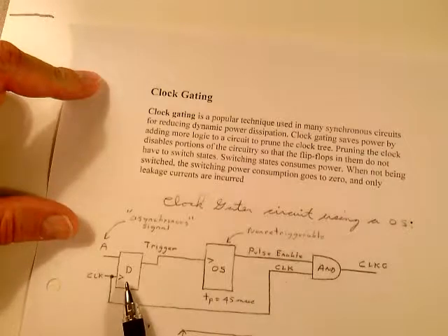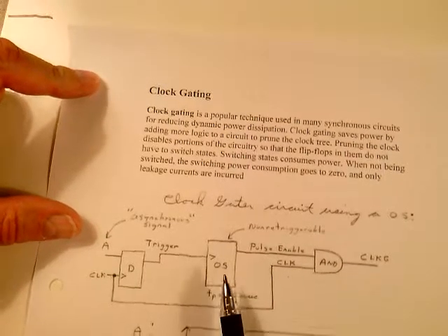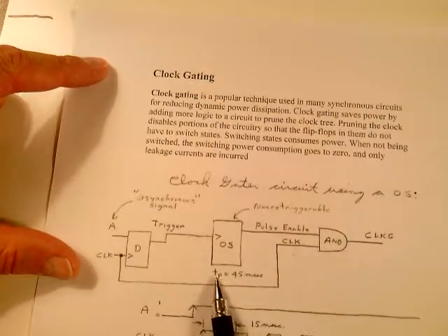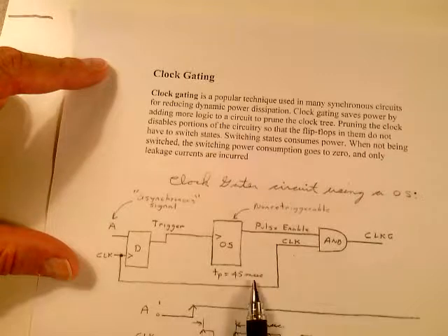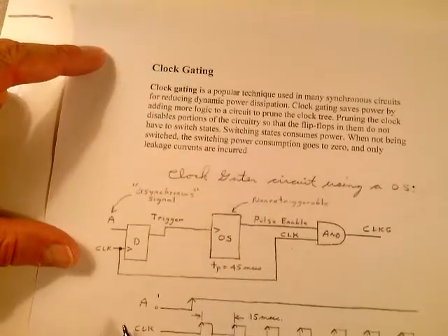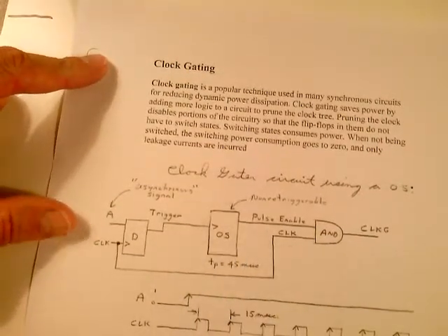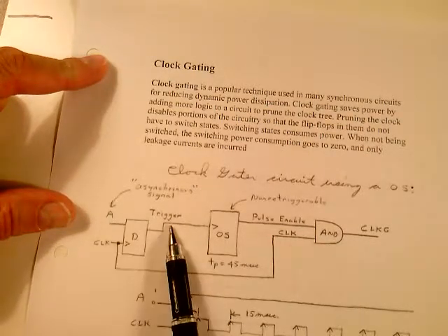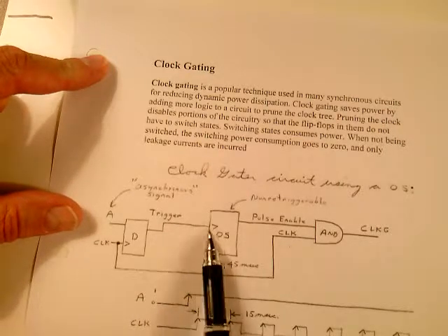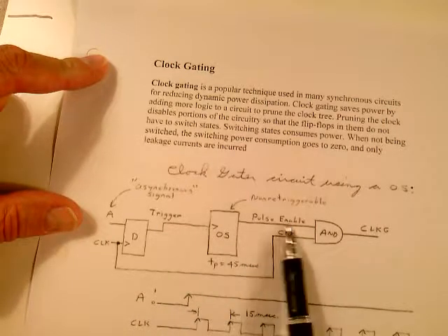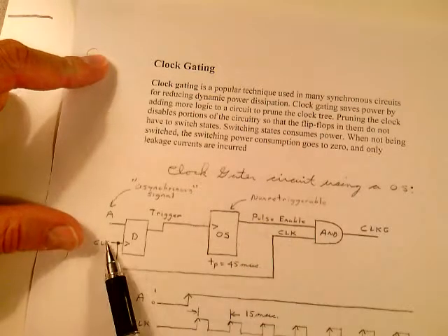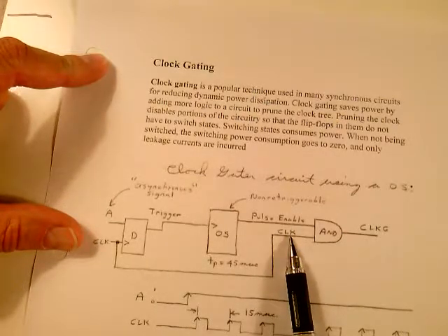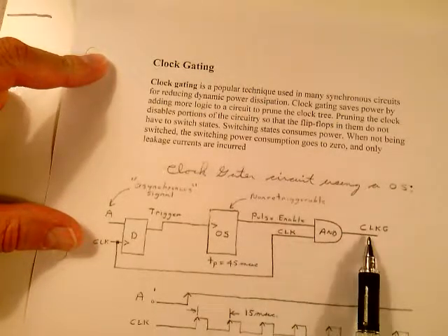Well, if you notice here, what we're going to do is set up a one-shot multivibrator here. A monostable multivibrator is a one-shot with a T sub P of 45 milliseconds. You could pick values of R and C to give you 45 milliseconds. It's non-retriggerable, don't forget. And out here you have an asynchronous signal that when the clock comes, it just basically provides a trigger to the one-shot, and you enable the pulse. This is a pulse-enable circuit that enables this clock through this AND gate. When this goes high, clocks can come through. When this goes away, the clocks go away.